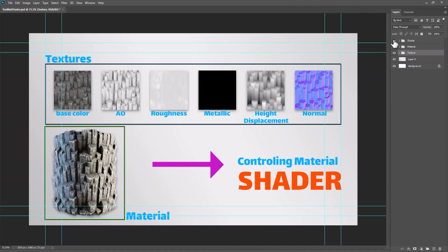Roughness. It is determining how light interacts with a surface. A surface can be glassy or semi-glass. AO or ambient occlusion, a shadowing technique used to make 3D objects look more realistic by simulating the soft shadows. Displacement, create depths on surface. There is an important thing. Your surface must be high poly mesh and normal. Normal maps are a type of bump map that can add detail on surface. Unlike displacement, they don't need to be high poly.